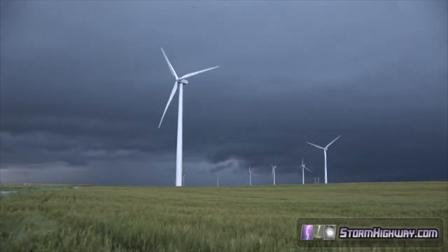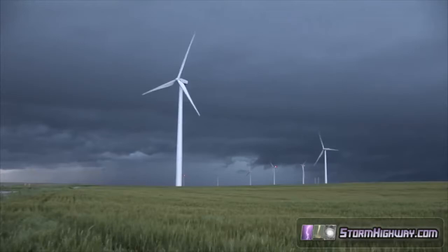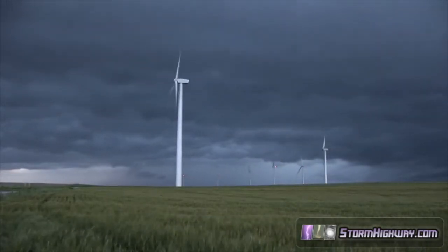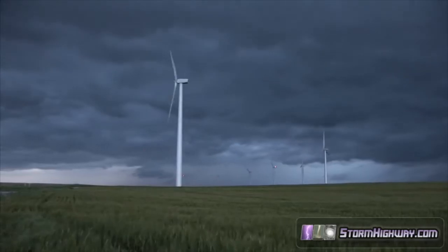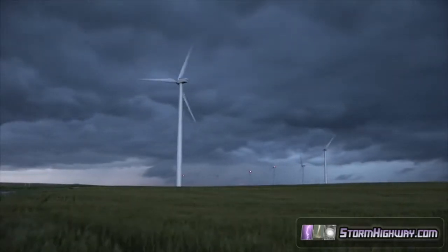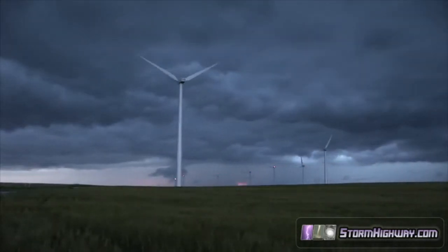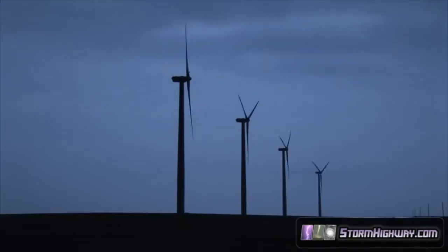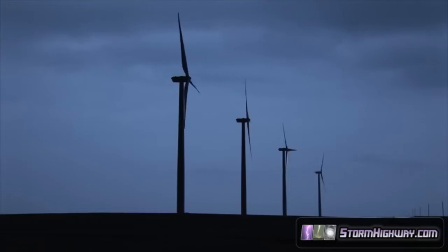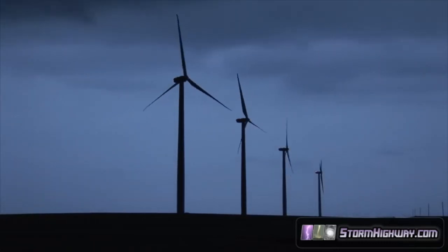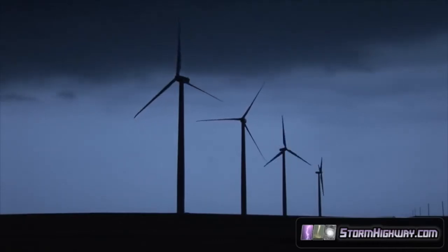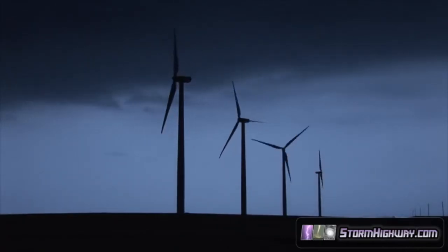A 30-year fatigue life for the wind turbine would be about 1 billion cycles, with turbines generally having 30 to 60 rotations per minute. It has also been underestimated how erratic the wind speed and direction would be. The turbines were originally tested with a relatively uniform incoming wind, with slow changes, similar to how planes are tested. However, it was found that on Earth's surface, wind changes drastically in both time and space, causing extreme turbulence-induced load on the blades.